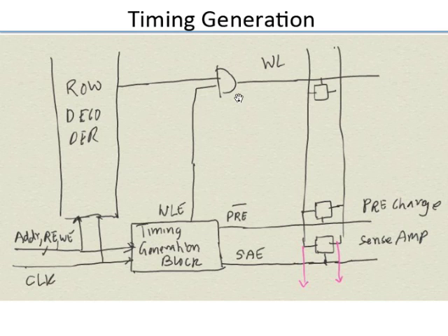after the decoder. But then you might have 8 bits of address, or maybe 10 bits of address, or even 20 bits of address for a megabit. Then the number of outputs of the decoder is an exponential growth. So if you put a pipe stage after the decoder, the number of flops required goes up exponentially, and you have to send clock to all those.